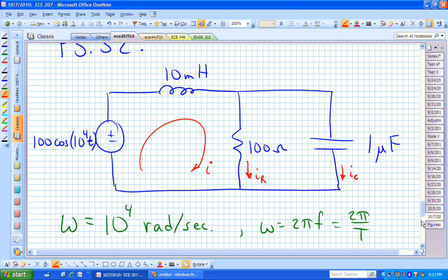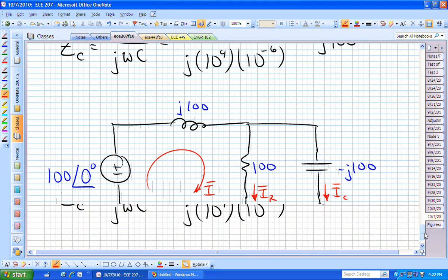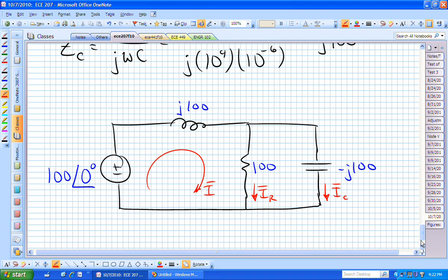We're shaking this sinusoidally. Because we're doing that, we can now analyze or think about what's happening with all of these currents and voltages. We know that they are shaking or moving at exactly that same frequency because this is a linear circuit. We know the current and voltages on these capacitors and inductors remain at that same frequency. That's why we sort of pulled that omega to the side and put it on our napkin, and it's buried now in our phasor relationship. But it did influence, because of what we just derived earlier with respect to our complex impedances, we now know how to relate that frequency and the L's and the C's and the R's to these new quantities that are now in the frequency domain.